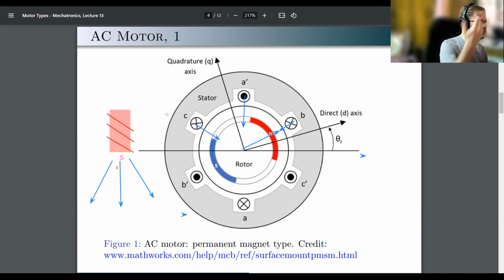If we allow 360 degrees rotation, it will be 6 different positions that the motor will achieve. One facing one source of magnetic field, then another one, then the same, but with the orientation changed. So 6 different positions that it can achieve. So this somehow implies that there will be a 60-degree gap between those sources of magnetic field, right?